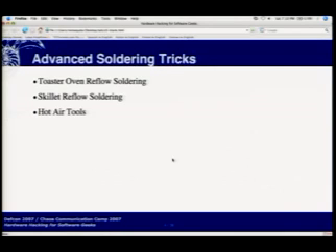The industrial equivalent to that is wave soldering, where you've got a whole wave of solder, kind of like the wave coming out of an aerator in a fish tank, where they've got a special coating on everywhere but where the solder is supposed to stick, and that's how they put all the parts for the assembly on top of the PCB when the board is ready.